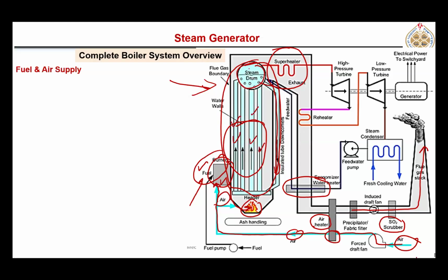So in the steam drum, steam is separated, saturated steam. This saturated steam is going into the superheater. Right from the superheater, this steam is going into the turbine, and these are the exhaust gases. Now, if you are using a 2-stage turbine with reheater, here you can see this reheater. So this steam is again sent to a reheater. After the superheater, you can install a reheater, and then it goes into the second stage turbine. And these are the hot gases.